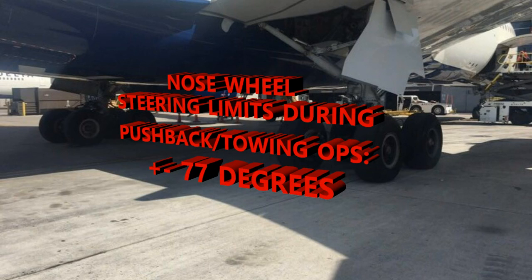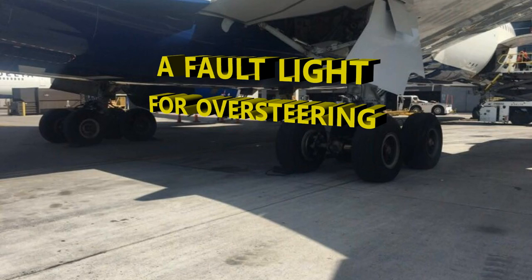Here we're talking about a deflection limit of plus or minus 77 degrees, either left or right, when you're towing or pushing back the aircraft. You don't want to go beyond those limits, because obviously you're going to cause damage. So just be aware of that.